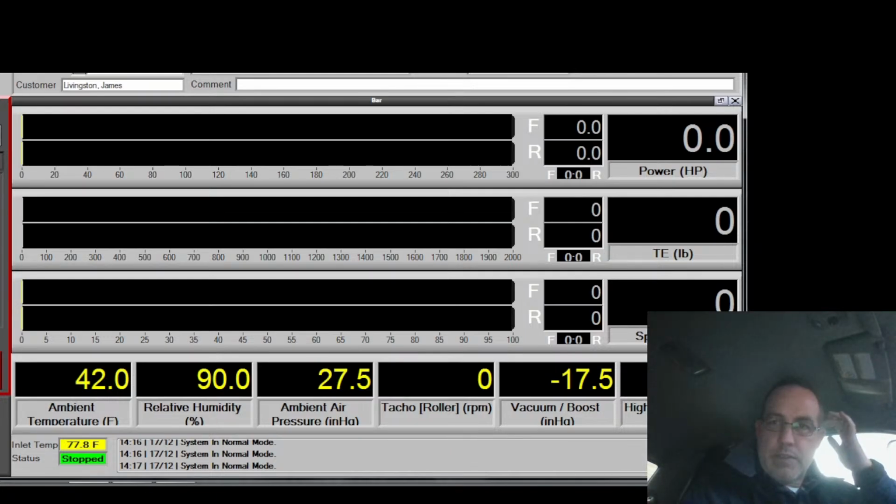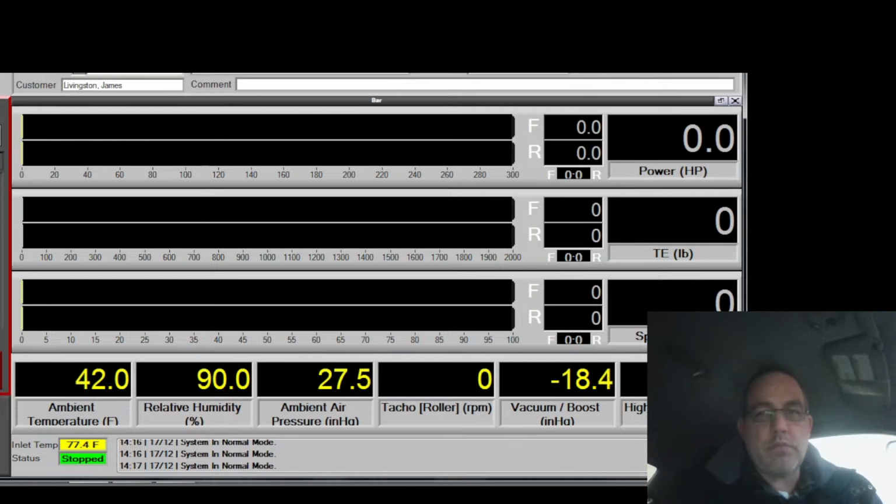I mean, I just put a 4-bar in it and haven't tuned it for the 4-bar. I put the base calibration on it, but that's it. But even then, when you do that, there's still always just a little bit that it's off. Yeah, idle's definitely lower than I want it to be.